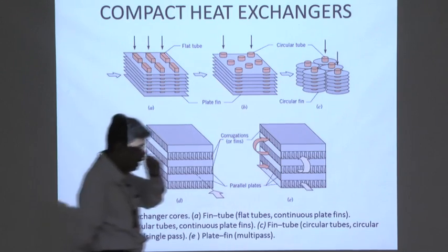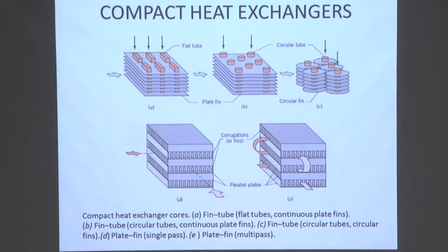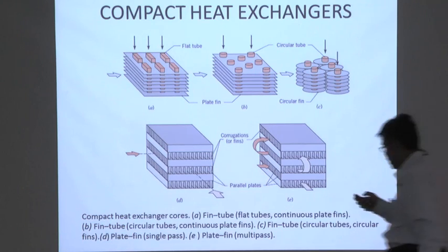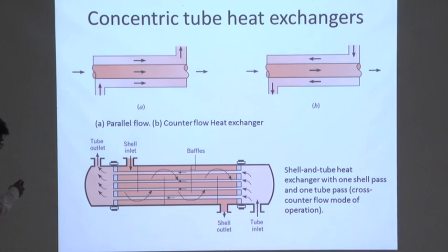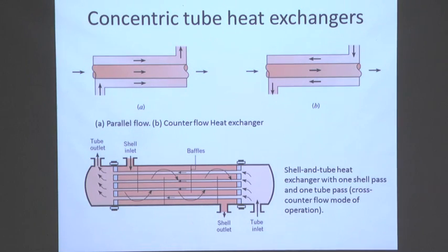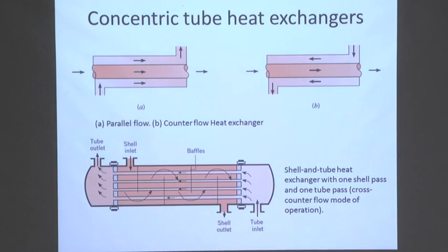A simple example I am telling you, that if you have a big long rod of diameter d and heat exchange takes place between the two fluids, that is a shell and tube heat exchanger. So you know that if you go on increasing the length, you have more surface area, pi dl. Pi dl is more. But for the same length, if you make a helical coil tube within a small space, you have more surface area. Sometimes by changing the flow field, we create more surface area virtually by creating the residence time. So anyway, you have to provide something either by geometrical surface area, by enhancing the heat transfer by providing extended surface area, or the flow field itself, so that we have compact heat exchangers.